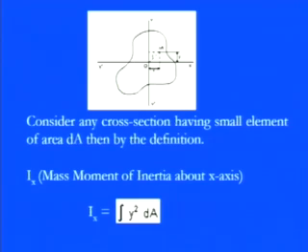So to calculate the second moment of area, we come back to the same structure, in which O is the origin, coming from both of the axes, x to x dash and y to y dash. Then we have a small segment, for which there is a small element of area dA, and for that we have the distance r. So r, like the polar coordinate, can be related to the x-y Cartesian coordinate. It has the distances x and y, so r is nothing but the square root of x square plus y square.